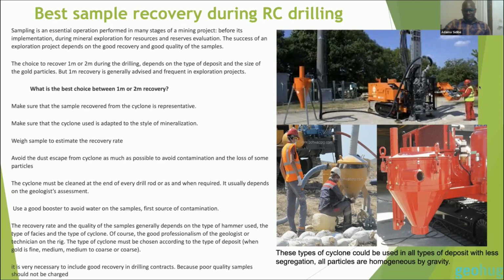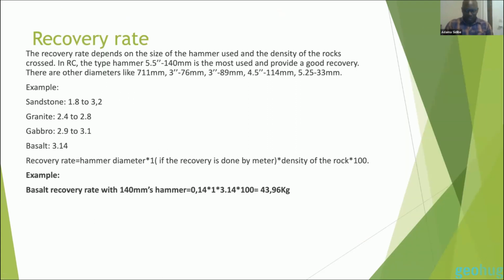For me, this type of cyclone is better for all types of deposit. Okay, as we said above, the recovery rate is essential in assay drilling operations. The recovery rate depends on the size of the hammer used and the quality and density of the rock crossed.